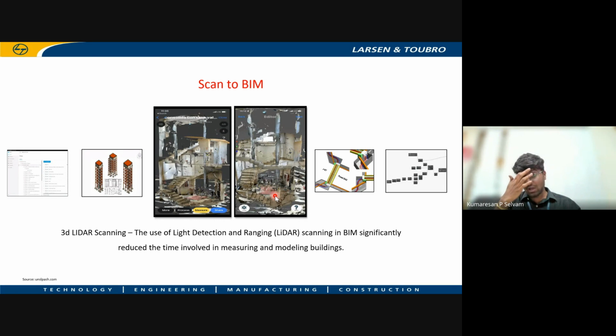So here, when we asked the client for detailed drawings and everything, they told us that there is no drawing available and there is no proper documentation available. So we went with the iPad, and in the iPad there is LiDAR technology where you can scan the building, and that whole building will be recorded as point clouds, and then it can be developed into a BIM model, and it can be used for further expansion and all other applications.